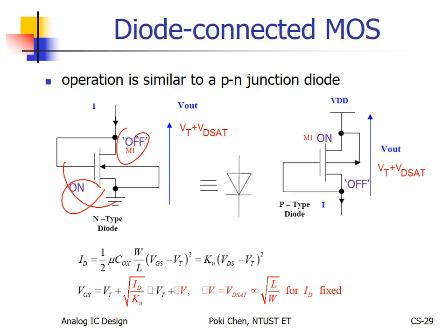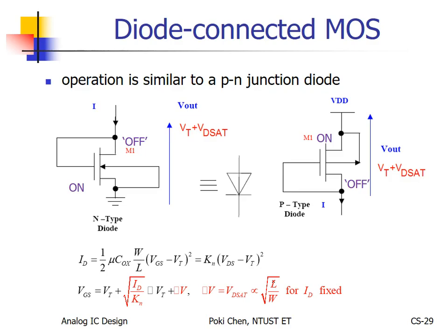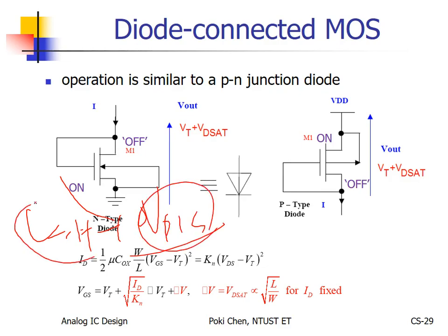You also need to keep in mind what the requirement is for the operation voltage. VG needs to be VTH plus delta VDSAT or so. So not only VTH higher, but with some voltage difference to support the operation in the saturation region. But how much is such a delta VDSAT? You can see that.